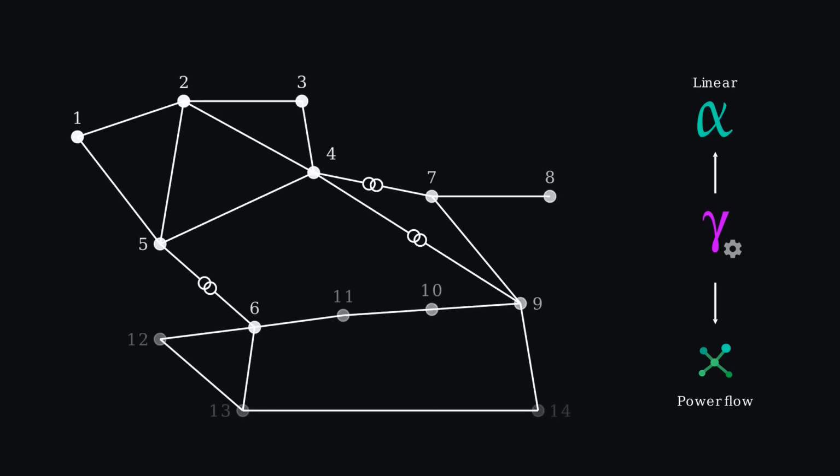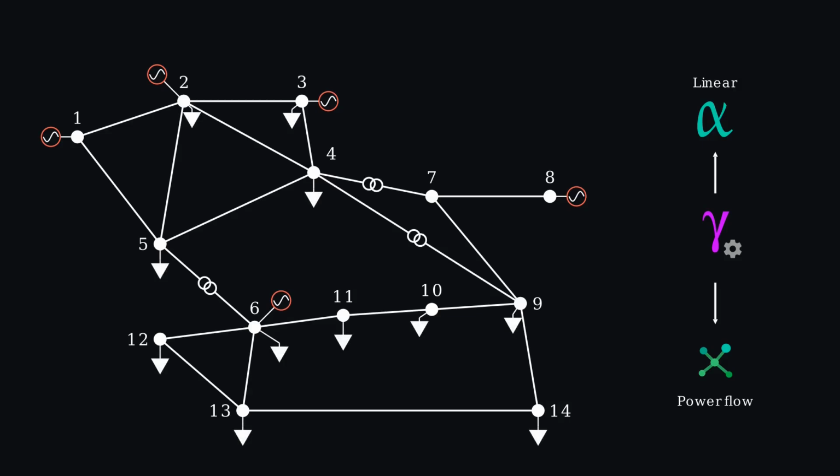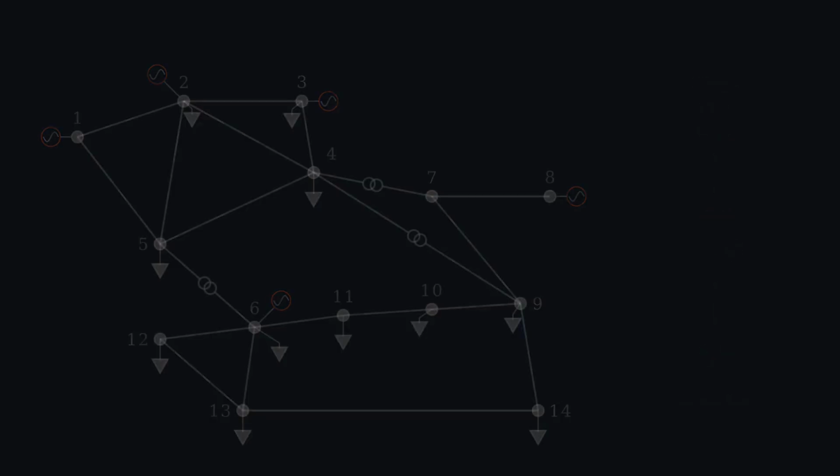The first is the power flow-based method, where VeraGrid solves a power flow for each outage. This is the go-to option when you need detailed results and want to capture voltage and reactive power effects properly. The second is the linear method, which uses a DC or sensitivity-based approach to estimate post-contingency flows. Being faster, this method is ideal for rapid screening and ranking, especially when you have a large contingency set and want to identify the most crucial cases before running the full AC analysis. An important point to note is that due to theory on linear analysis, a maximum of 2 contingencies can be studied at the same time.